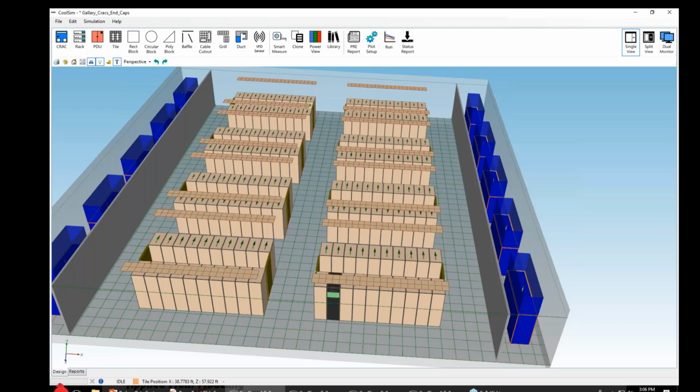Now, having said that, it's a cost issue, because it's cheaper to put one pressure sensor under the floor than it is to put 3 temperature sensors, one per rack. That cost adds up quick. But from a control point of view, it's a better control because you're actually measuring what it is you're trying to control, and that's rack inlet temperature.